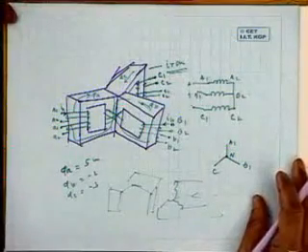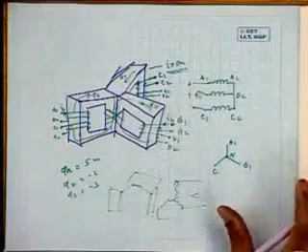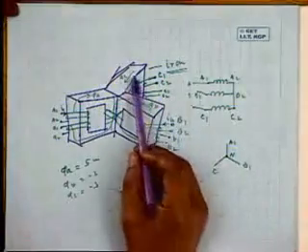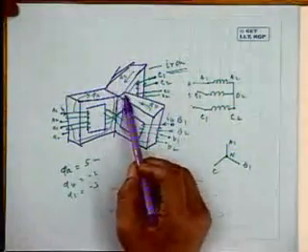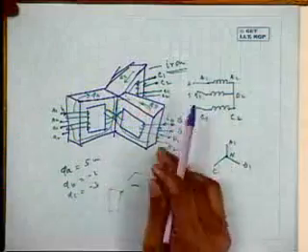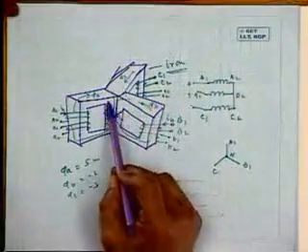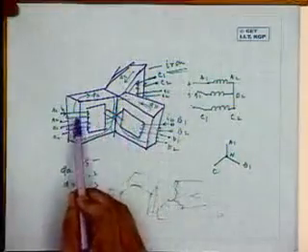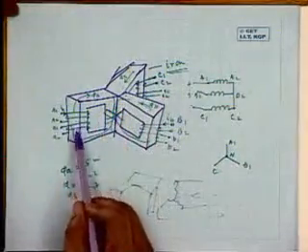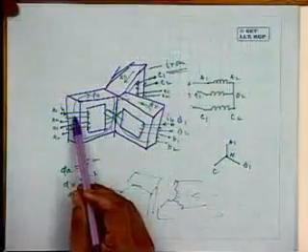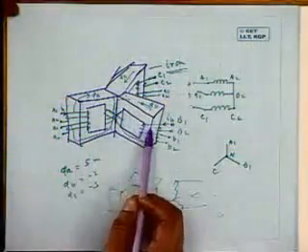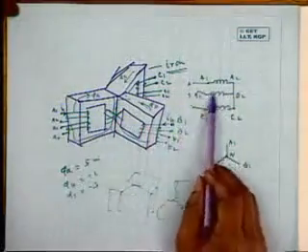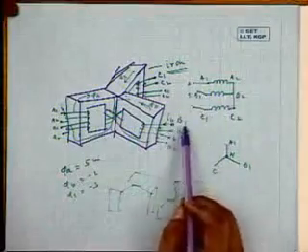But also a 3-phase transformer can be constructed as a whole. So we were starting that. If you imagine that 3 single phase transformers are placed like this with a central common core, and each outer limb is having 2 sets of winding. One will be primary, another will be secondary, and the primary turns are equal, that is A1, A2, B1, B2, C1, C2 equal.